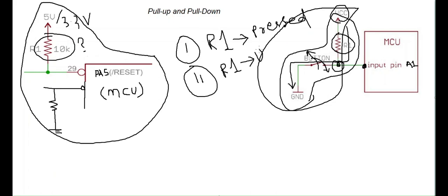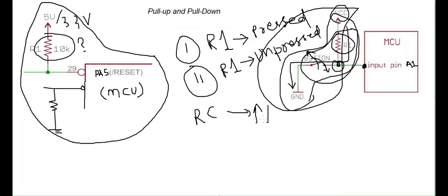And also one more thing I would like to say. Whatever system is feeding this input pin is mostly a capacitive couple, and that will form one RC filter. And you know that an RC takes some time to charge and discharge. Now when you are using a pull up on a very high speed signal, let's suppose that signal is changing very fast and it is USB, if you keep a very high resistor value, that may limit the speed at which the input pin will change its state. So mostly we will see on the USB lines the pull up values are from 1 kilo ohm to 4.7 kilo ohm. So you have to take care of all these points while deciding what value to keep.